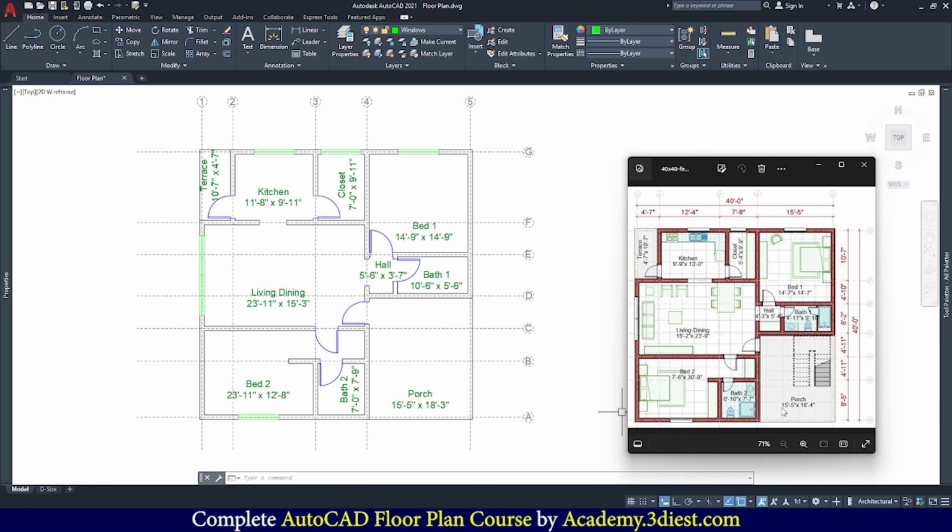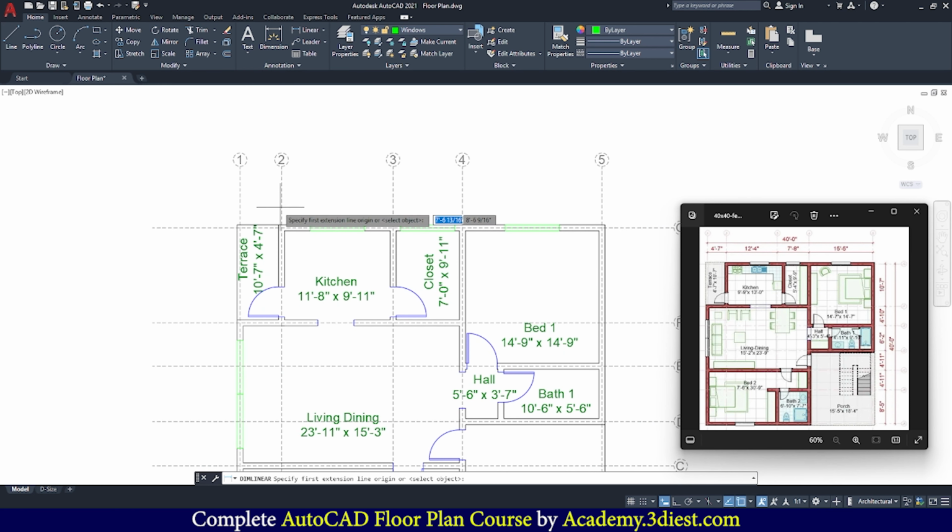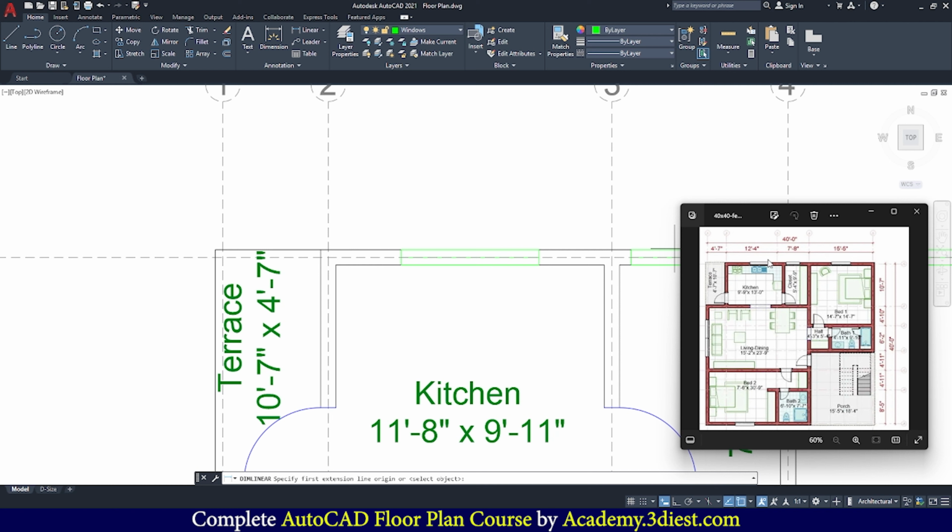Before that, I want to add these values, this dimension, to our drawings. So if someone wants to read our drawing, he or she will have a complete idea about all the sizes and measurements. This we can do using this tool called dimension tool. Inside this dimension annotation panel over here, we got a tool called linear dimension, align dimension, angular dimensions. I will activate my linear dimension tool and then we'll start dimensioning these grids, as you can see in this image.